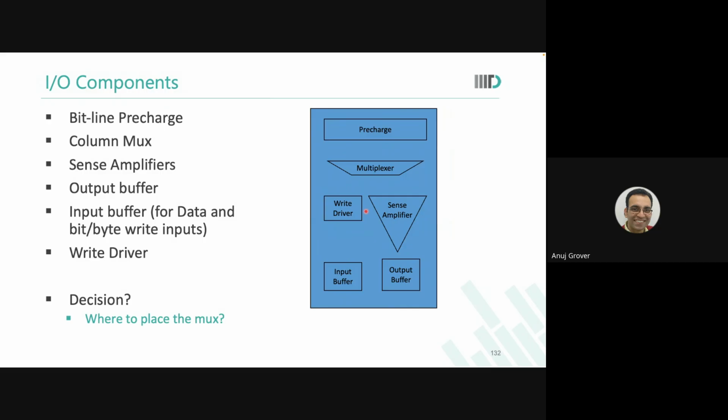Are you with me? If you really want to take it to the bitline level, then where we said column mux, you can also say column DeMUX. We basically make one circuit which acts as both mux and DeMUX. We call it column decoder. But you could also call it column DeMUX. Or you can say that if I do not give it both the functionalities, then I need something for the write operation also. Because for us, area is diamond, we don't want to waste area. We say, okay, this one circuit will do both the jobs.